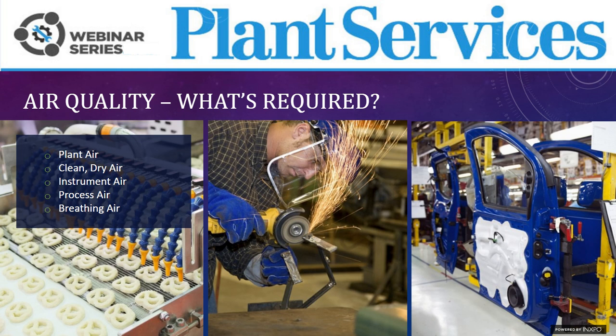ISA S7.3 describes instrument air in terms of system design and specifications, but it's still rather broad as it doesn't prescribe specific levels of air quality. Further, it specifies that pressure dew point must be 18 degrees Fahrenheit below the lowest ambient temperature.